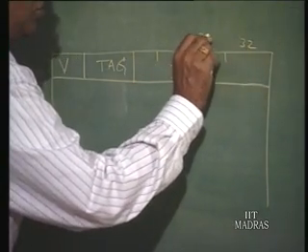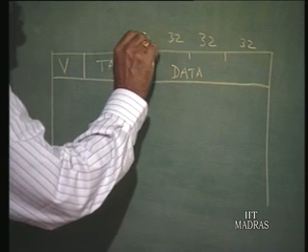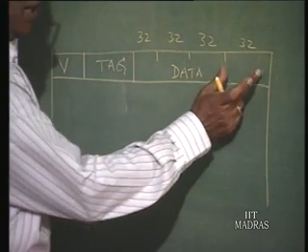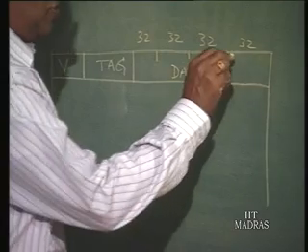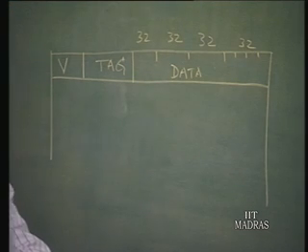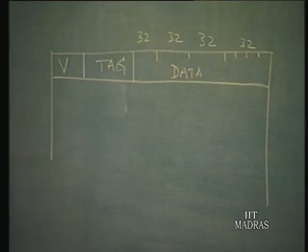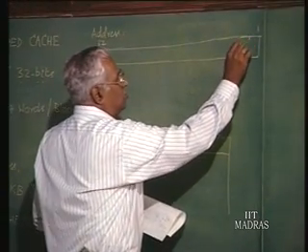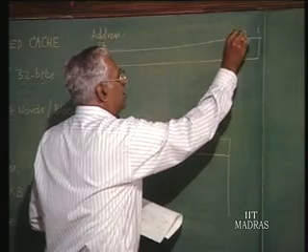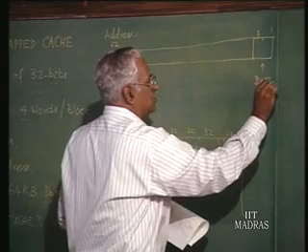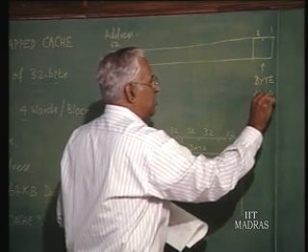This is the 32 bit data, this is another 32 bit data, this is another 32 bit data, this is another 32 bit data. So, we have 4 of these. Now, earlier we had only 32 bit in one field. So, actually 32 bit means essentially that consists of 4 bytes. So, as before, whatever we had worked out earlier holds good now. For identifying which of these 4 bytes, we have to allow 2 bits in the address, and that we called it as byte offset.